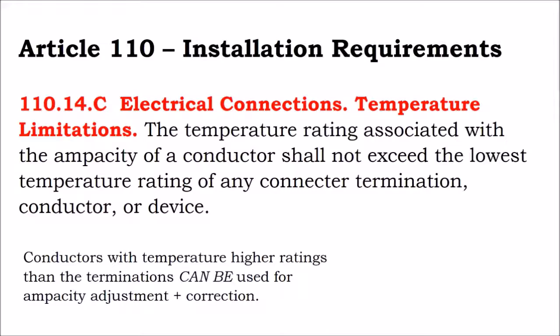Okay, other installation requirements, connections. The temperature rating associated with the ampacity of a conductor shall not exceed the temperature rating of any other connector, termination, conductor, or device.